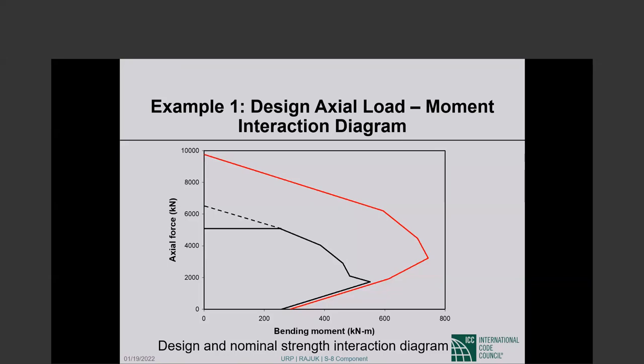What I suggest is, as I suggested the other day, you draw the joint to scale at the design office, and if you find that bars don't fit, or after you put the bars in, concrete doesn't go in, then change something in the design. You cannot just bend bars or set bars aside, or drop bars.